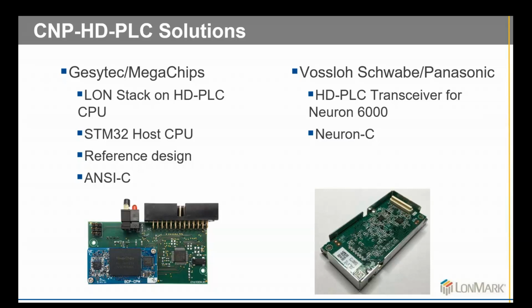We had been asked for 8051 based designs. It can be, for instance, Microchip or something like that. And we are selling that as a reference design. In that case, if you do it in that way, you are programming in an ANSI C environment, which is slightly different from what the LON developers know from Neuron C.